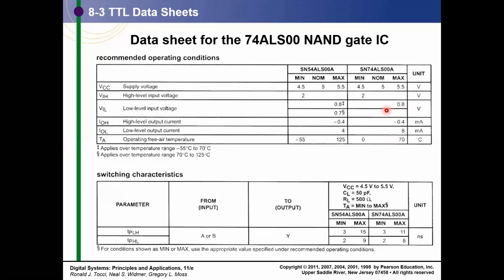There could be a question why there are two values for VIL but not for VIH. It just comes from the measurement technology. You do a measurement on several thousands of devices and then you draw from the statistics.